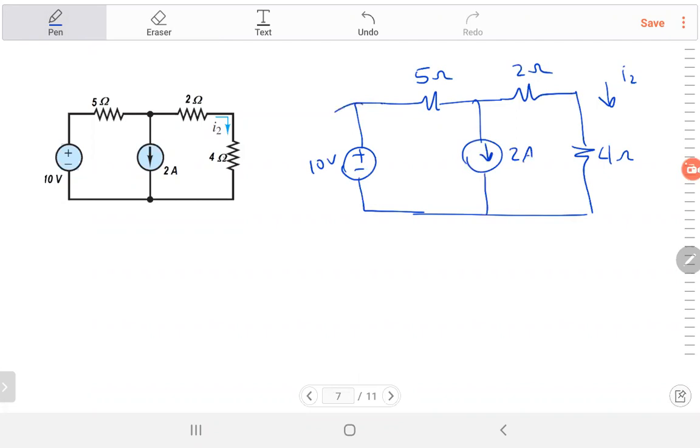I want to put 0, so I make a short circuit, so no current will go there. When we say you're going to kill the voltage source, just replace it by a wire. Just simple, put a wire. If you want to kill the current source, remove the wire. That's easy, right? Current source, you remove the wire. Voltage source, you add the wire.